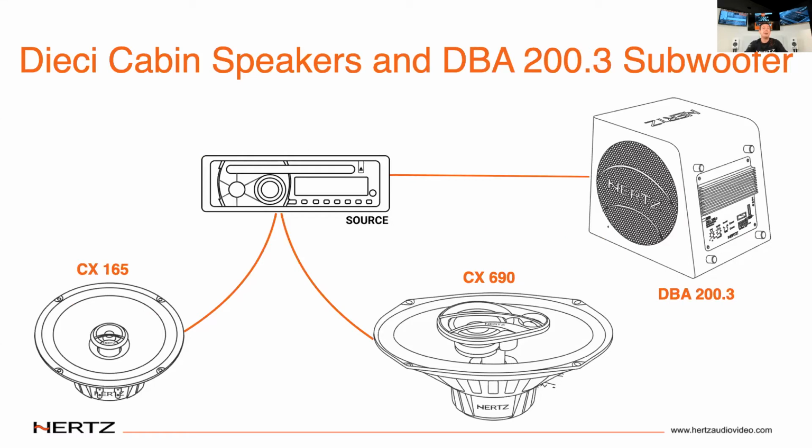Now the cabin speakers have a trunk subwoofer helping them out. We talked in episode 1 about how low bass has excursion required from the speaker. And if you use a dedicated subwoofer, it's the best way to address the excursion problem. And that way, we're not asking the cabin speakers to travel beyond their safe limits.